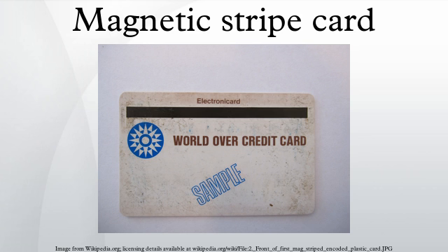The manufacturing process started by first applying the magnetic stripe to the pre-printed plastic cards via the hot stamping process developed by the IBM IRD engineers. This operation of applying the magnetic stripe to the plastic cards was done offline in another area of IBM IRD and not in the secured area. The cards were then brought into the secured area and placed in a warehouse at the beginning of the production line. The tape reels containing the data were then installed on the modified IBM 360 computer prior to beginning the encoding, embossing and verification of the cards.